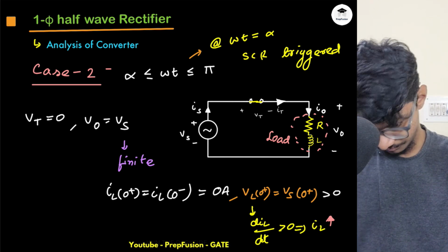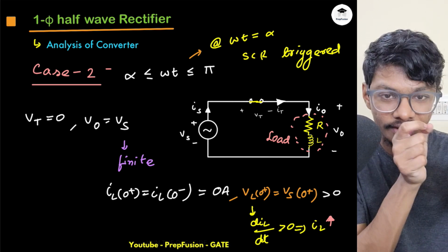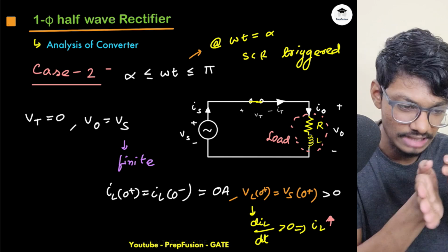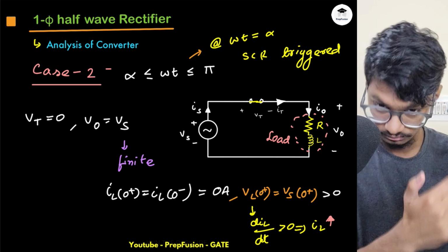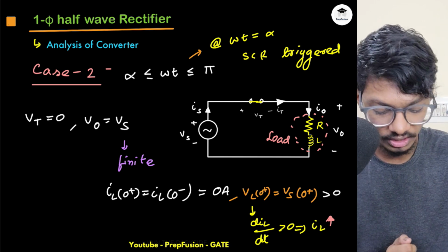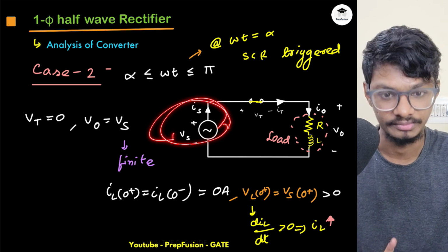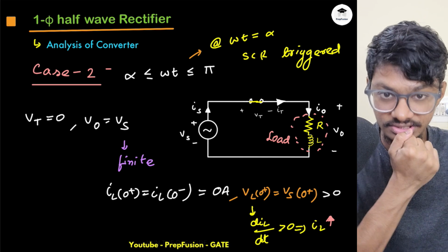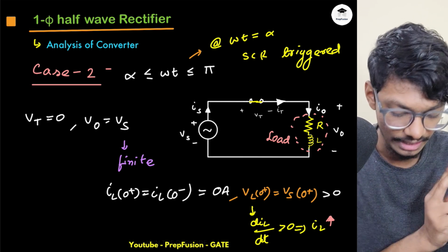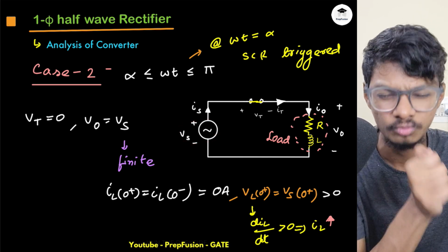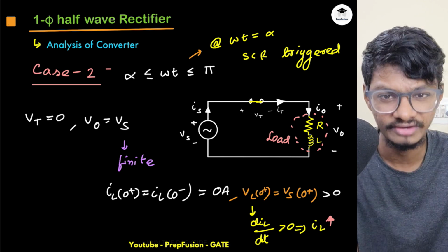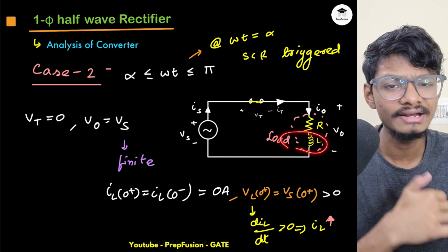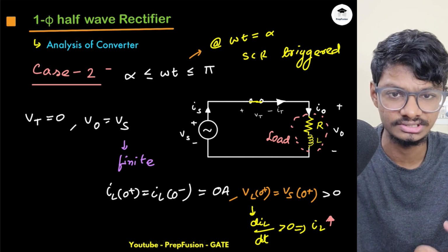So just after omega t equals pi, it will go to minus 0.1. So this polarity has flipped. But remember, inductor current cannot change instantaneously unless an impulse voltage is applied. And what is the voltage? This is some very small, finite voltage, not infinite, 0.1 volts. So the inductor will never change its current instantaneously.